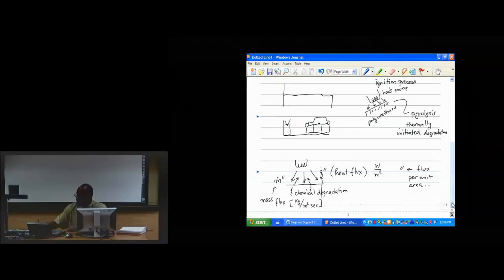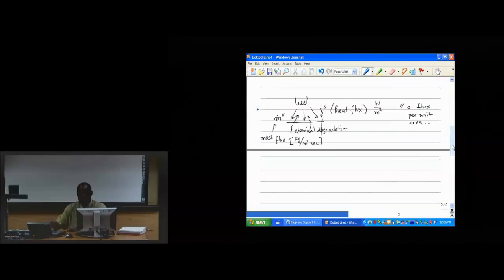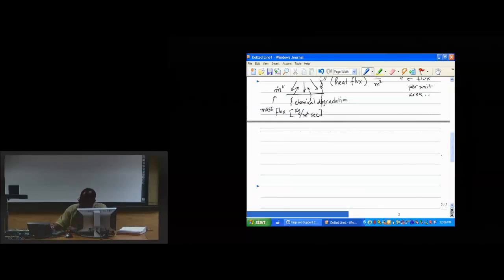And it is in fact these volatiles that we consider the fuel for a fire scenario like this. So we have an ignition source that is intimate with a condensed phase material. It heats the condensed phase material until in-depth pyrolysis occurs. The in-depth pyrolysis creates this mass flux of volatiles. And at this point, we haven't said that there's a fire yet, but we simply have said that there's a mass flux of volatiles. So really the next steps are what happens to this volatile mix as it's coming out.